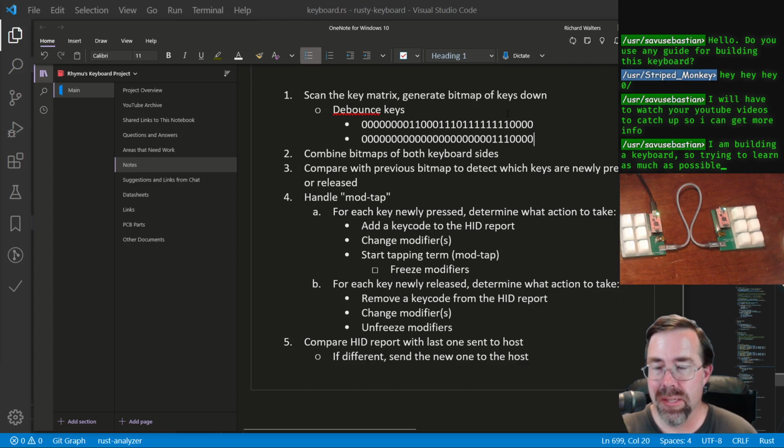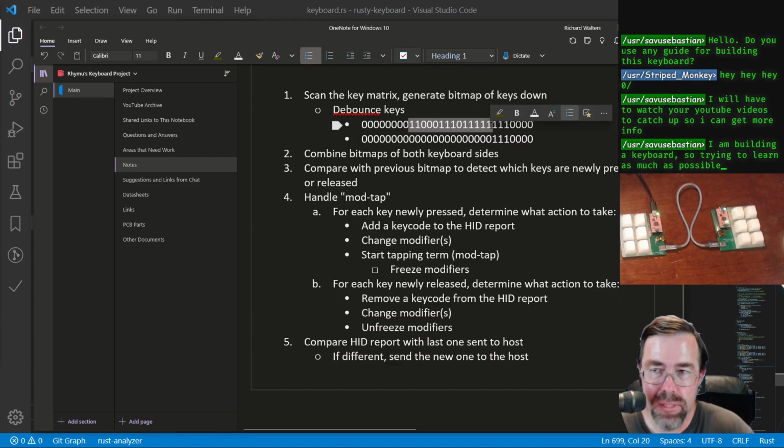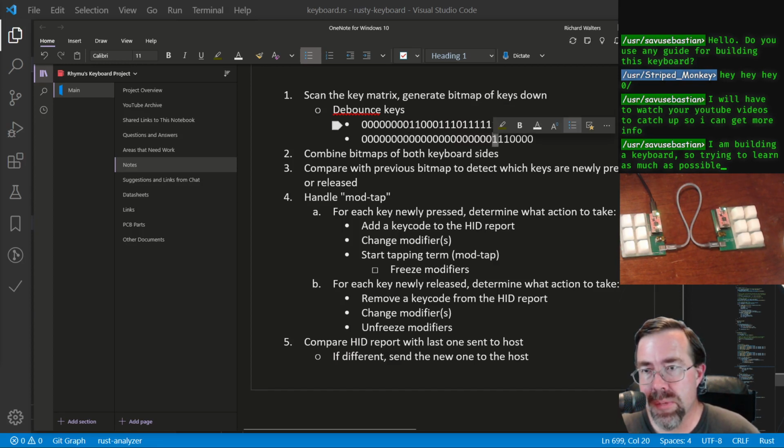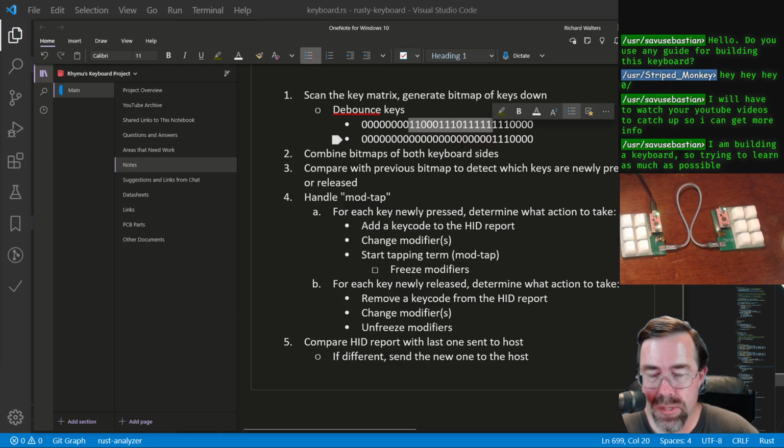You'd see that, right? So there's a little bit of delay here. If I actually press the key at this point, but we don't call it a key press until here, there's that many samples of delay. But my keyboard is telling me I'm anywhere from 10,000 to 40,000 samples per second. This is going to be an extremely short amount of time, like less than a millisecond. So I think it's fine.